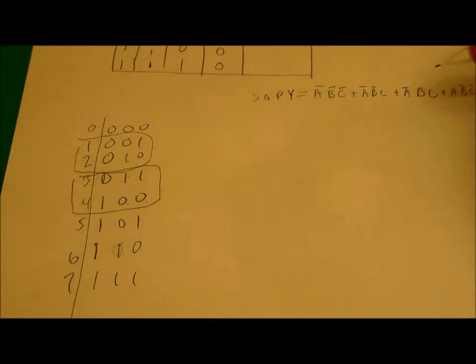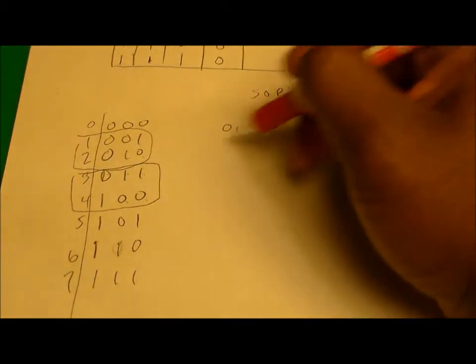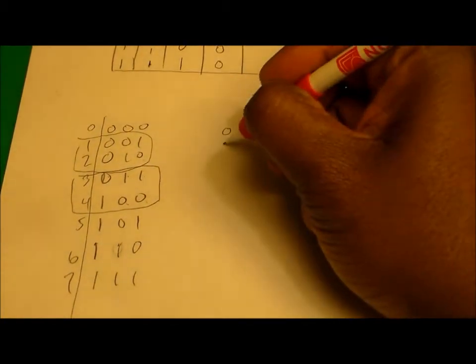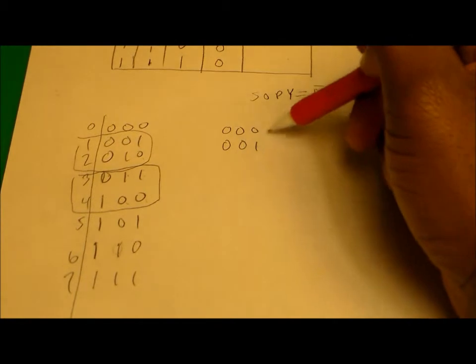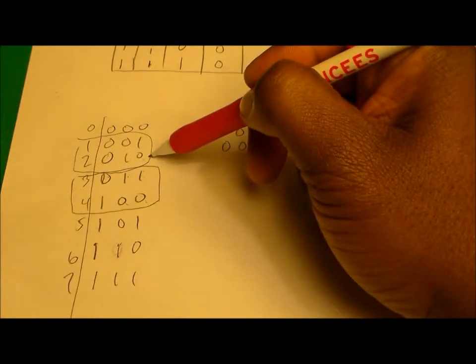So in essence, what we're doing is recreating, if you will, the binary system such that we have numbers representing each consecutive number, but there's only a 1-bit change in between. Okay, so let's start with just a 0, 0, 0, and that seems to be fine, of course. And then we have 0, 0, 1, and there's only a 1-bit change between there. But as we said, there's a 2-bit change in between here.